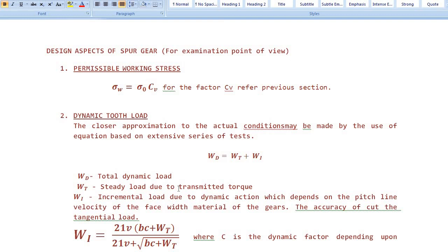The gear should have one of the important parameters, a common module. The pinion as well as the gear must have the common module, so the module must be the same for both gear and pinion. Otherwise, mating is not possible. Therefore, the module has to be designed in the design process.